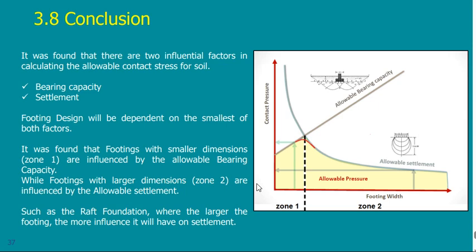Suppose you get the dimension of the footing 4 by 2, and you were assuming that the footing width at the beginning was 3. Now it is 2. So I will have to make another iteration, another trial. I will start here with 2 instead of 3, like the first time. I will go from 2 up till this point.